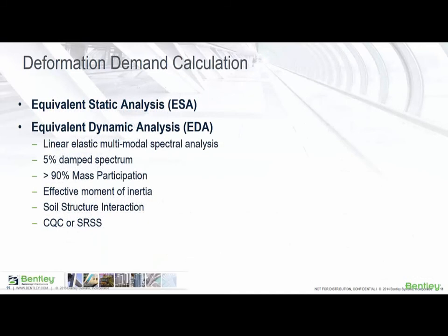Deformation demand calculation. The deformation demand can be calculated using the equivalent static analysis method or the equivalent dynamic analysis method. Both of these methods are similar to the single mode and multimode analysis methods reviewed under the force-based methods. The only difference is that here spectral displacement rather than spectral acceleration is calculated using the design response spectrum.